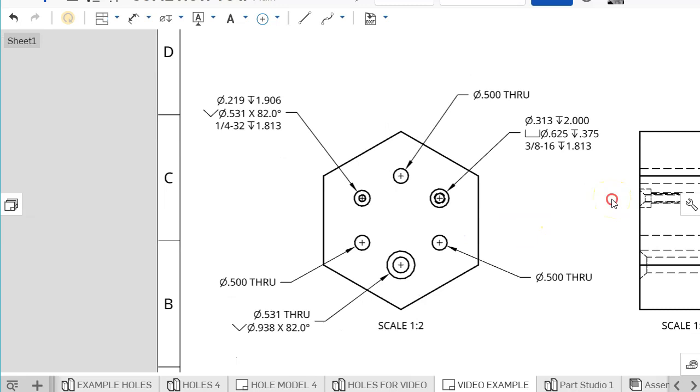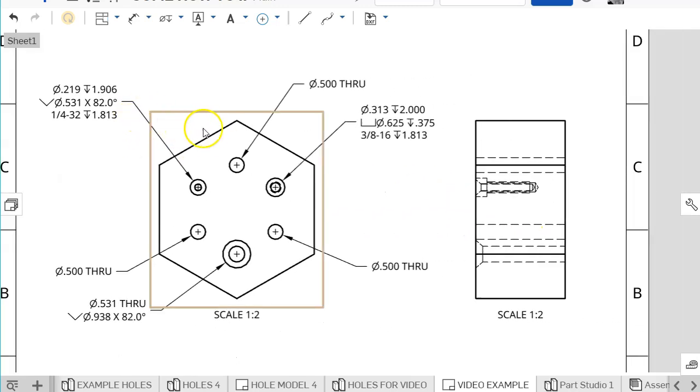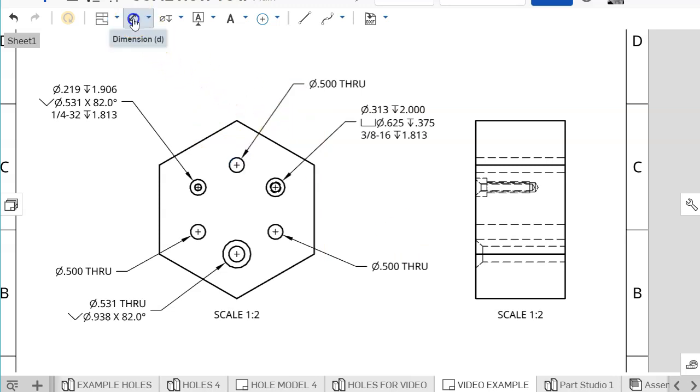Okay. If this were a circle, I would want to do a diameter measurement, but it's not a circle, so we're just going to grab this and pull it out to the side a little bit, make sure my 3 is centered. And then I'm also going to grab the thickness here and pull that out, make sure the 3 is centered. Good to go.